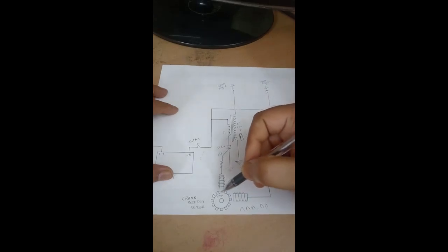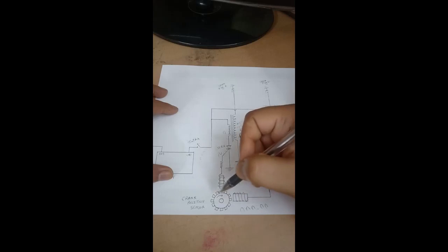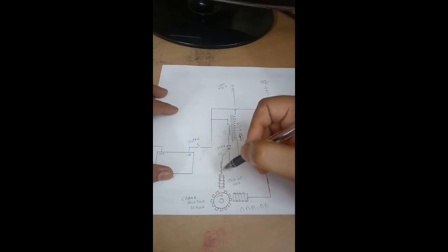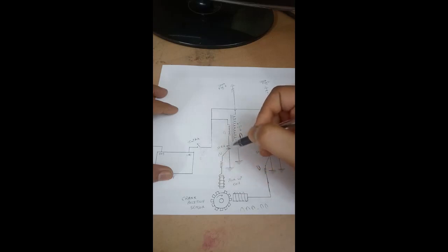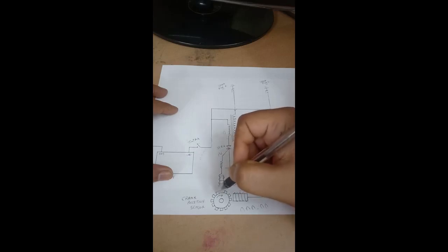So in this case, as the crank position sensor rotor rotates and aligns with the pickup coil, the pickup coil picks up the signals and puts the SCR in conduction and non-conduction form. Once the empty slot passes through this pickup coil, it again generates pulses like this.